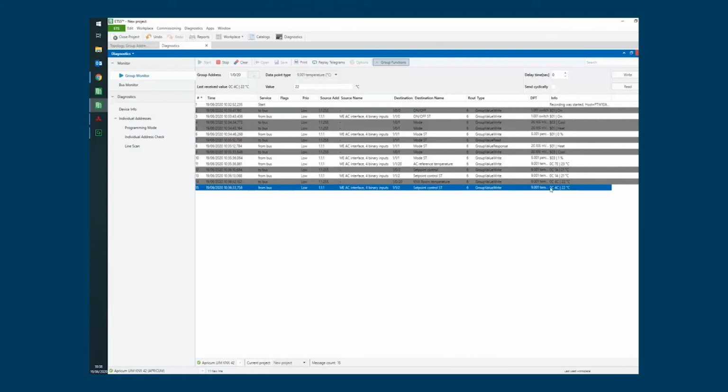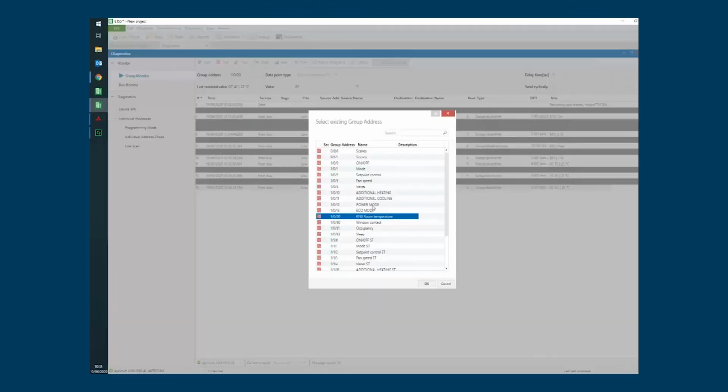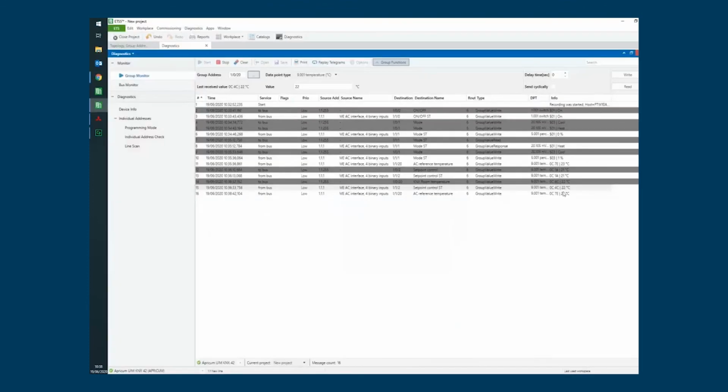And then it changed the feedback, because now the real set point in the AC unit is 22. So that's why you shouldn't link this feedback again back to the thermostat if you are using this virtual temperature function. Okay, we can see how it changes if we change the room temperature now. Well, this is a periodical report of the AC unit.